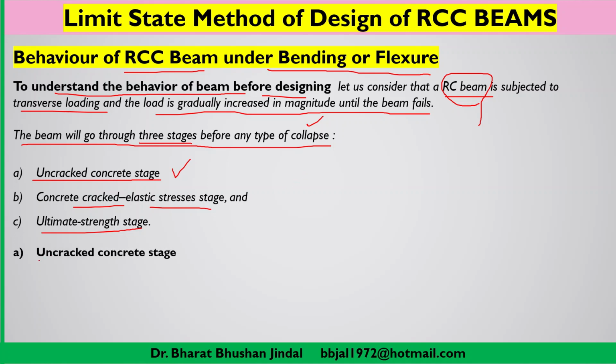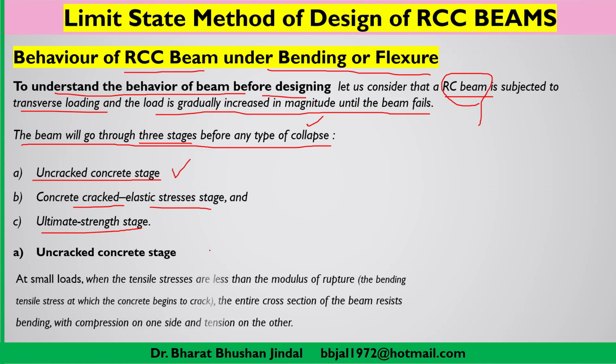Now let us go one by one. Very first is the uncracked concrete stage. Definition part or elaboration: at small loads, as we have already said that we are increasing the load gradually. So when the load magnitude is small, the tensile stresses which are developing in the member are less than the modulus of rupture.